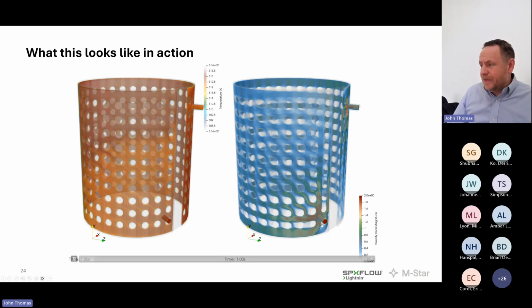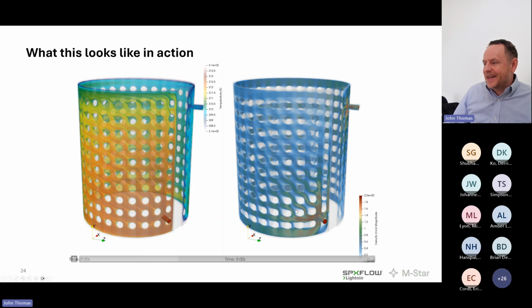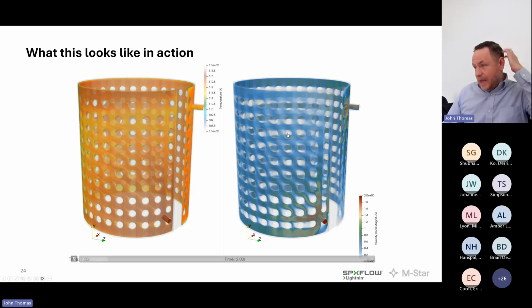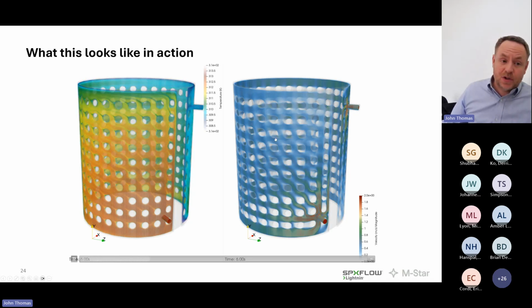Here is the corresponding velocity. We get some pretty good impingement here where the jet comes in, kind of snakes out like some sort of neural network, snakes out, eventually recovers on the other side as mass continuity demands. But through these regions over here, we have a pretty depressed velocity, which isn't a bad thing, but it can inform our jacket side convective heat transfer coefficient, possibly.